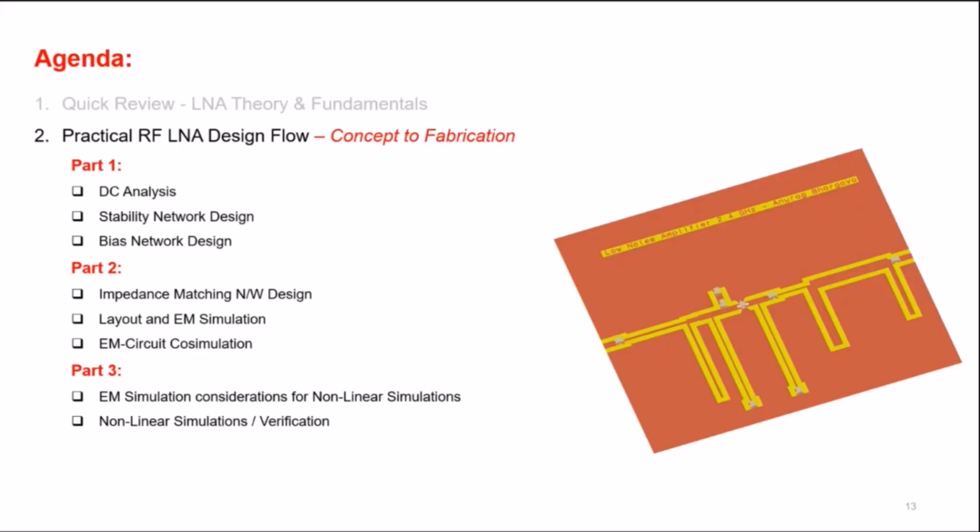In design of a matching network for MMIC, which parameter determines transmission line selection? I don't fully understand that question, but the impedance that you require will determine the line width and all that. But in MMIC, RFIC, usually you don't worry about it unless you're doing a very, very high frequency design like millimeter wave.